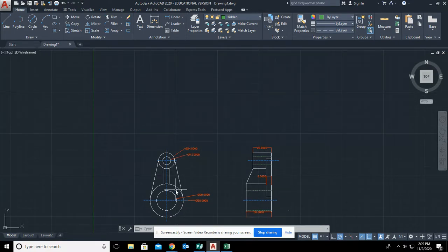As if you're looking straight down, the top view is going to be kind of difficult, so do the best you can. You're going to have the hidden lines for the outside of this circle, that hole, the outside of this hole. You also have hidden lines for the outsides of this gusset, and you'll have a hidden line for the face of this back plate. It'll go across the back. So do the best you can.